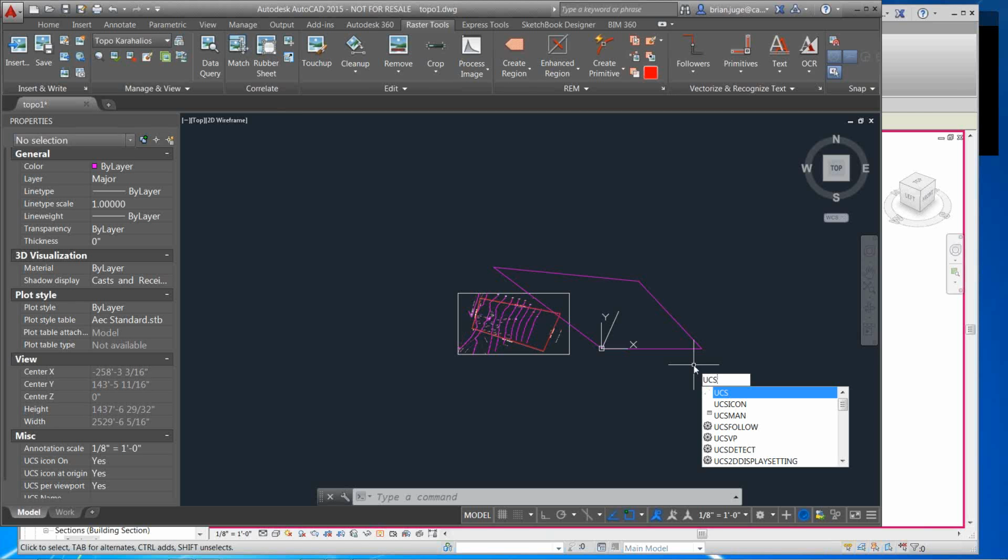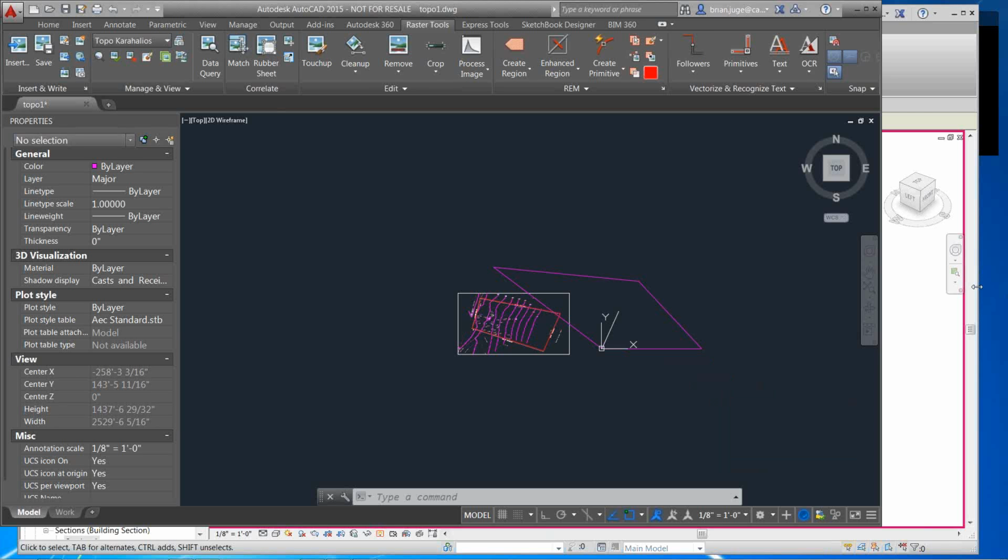Let's see. I think we might have some other questions on here. A general question, but very specific. I have a foundation wall with 4-inch foam on the exterior, 8-inch concrete, then a 3.5-inch framed wall. This wall is 3 feet above my slab and 3 foot 2 inches below my slab. I have unlocked my framed wall from the bottom and have moved it so it is on my slab. But when I do this, a footer is created on this unlocked portion of the wall. So in effect, I am given 2 footers. One is at the elevation of my slab, the other is at the proper level. How do I remove this second footer?